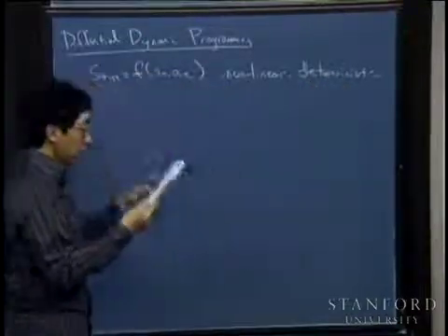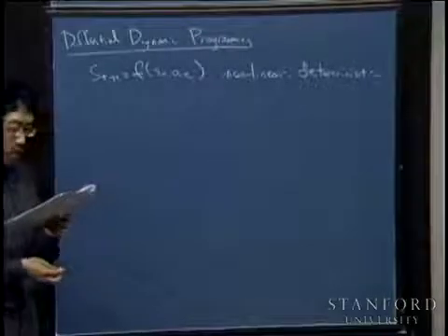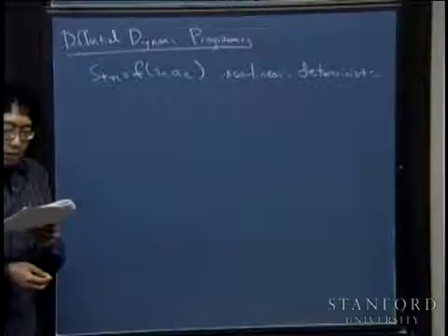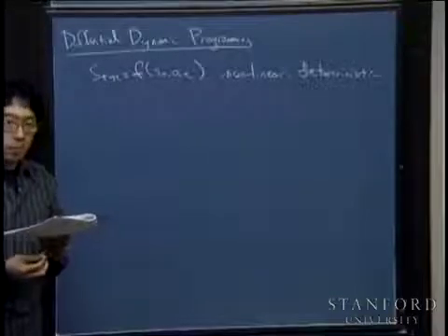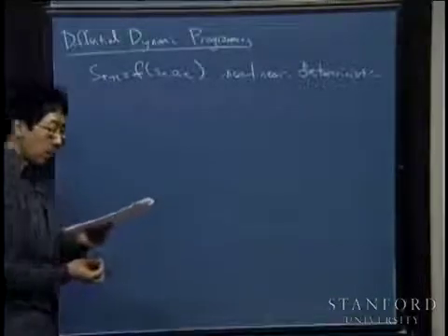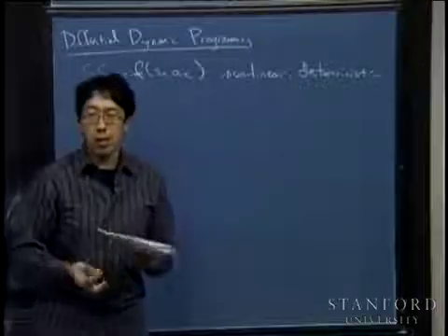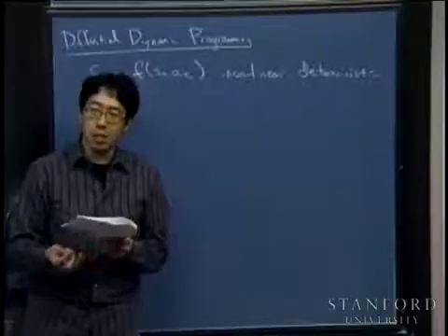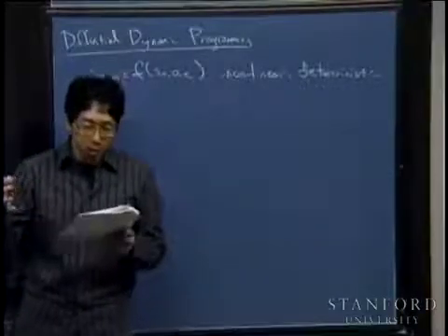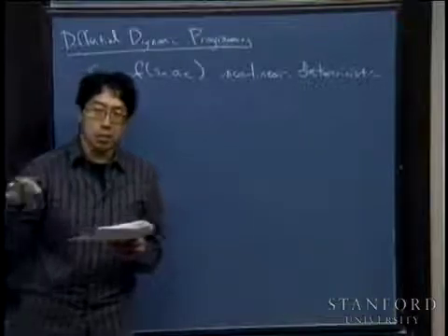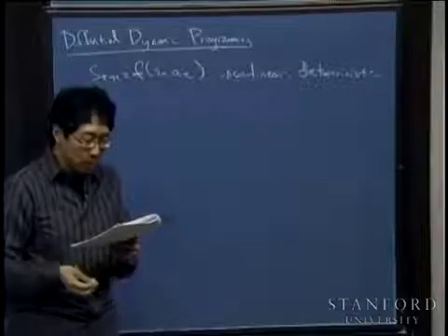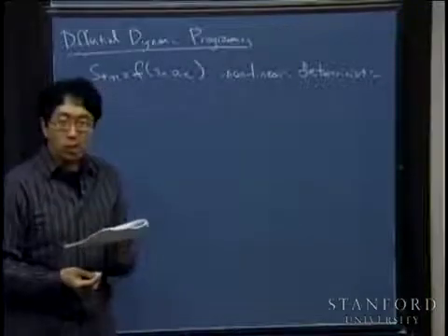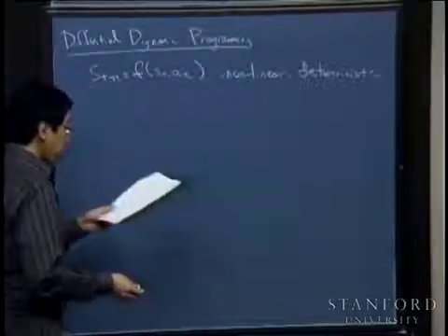But let's say f is nonlinear, and let's say there's some specific trajectory that you want a helicopter to follow. All right, so I want to talk about how to apply LQR to get a helicopter or a car or a chemical plant, where your state variables may depend on the amounts of different chemicals, mixes of chemicals you have in different vats, right? Whatever. It's very easy to think about a helicopter. Let's say some trajectory you want a helicopter to follow.